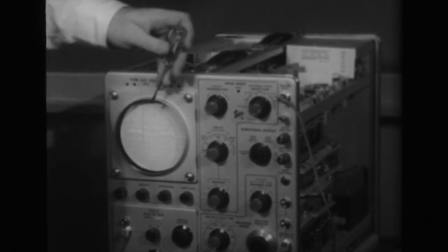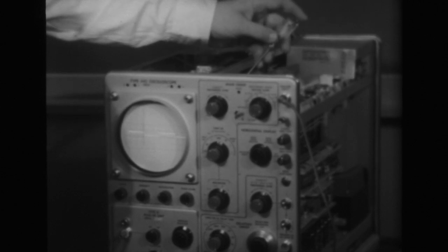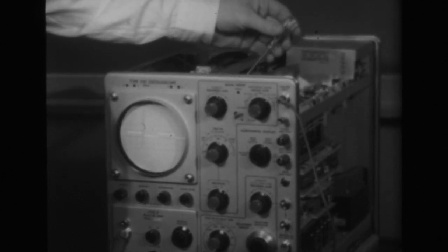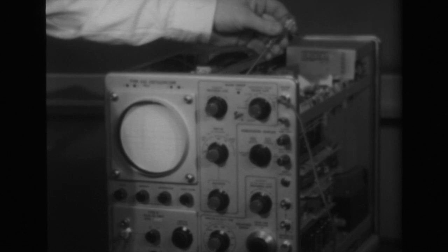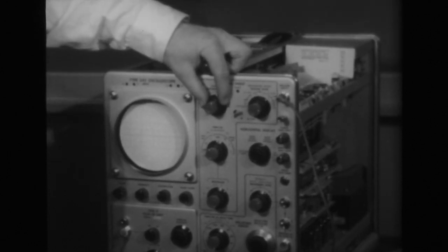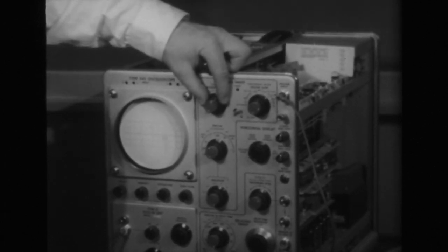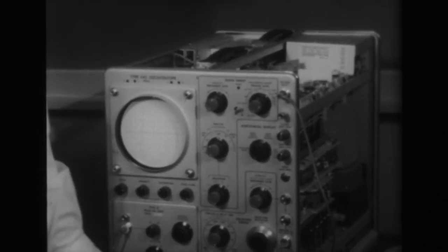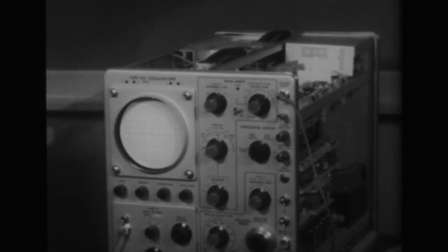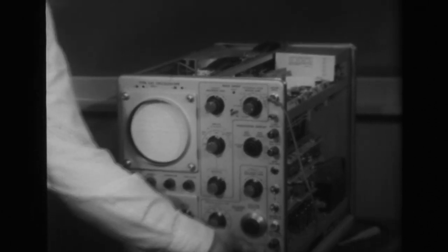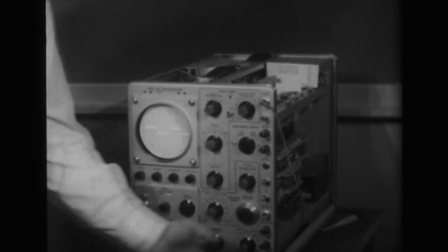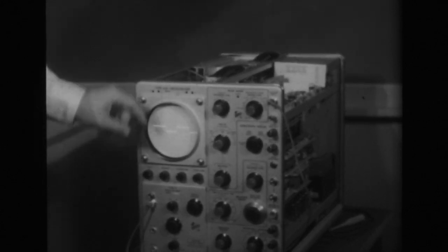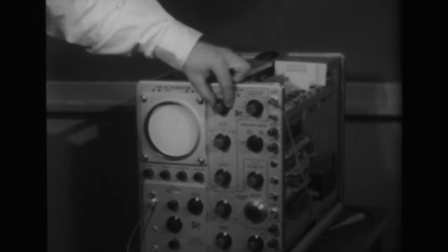fed in, as I now show, turn the trigger sensitivity pot about 5 or 10 degrees counterclockwise, and again check to see, by a very careful adjustment of the triggering level control pot, that you cannot obtain a stable display of the 100 millivolt square wave fed in. Next step, go back and verify that 200 millivolts will produce a stable pattern on the cathode ray tube. You may have to readjust the triggering level control to get that stable pattern.